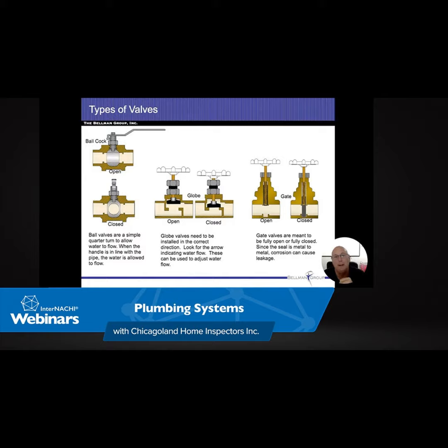But realize it's not just when somebody uses a toilet. That pipe goes straight to the main sewer line. So it's not just this house. It's every house in the neighborhood. Whatever sewer smells are in that main sewer line are going to come up everybody's vent stack. And if that's someplace where you're sitting and you can breathe it, again, I think it's unhealthy. And we should be extending these up higher.